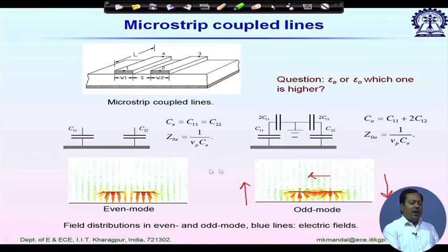Due to that we face problems when we design components, because in practice if we excite a coupled line system, we can always divide it into two parts, the even mode component and the odd mode component. These two excitations coexist and we will be having dispersion.